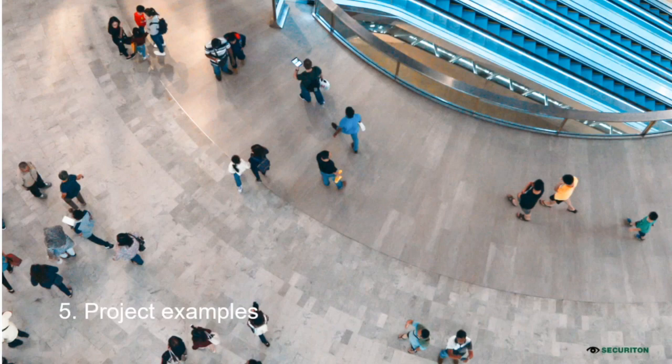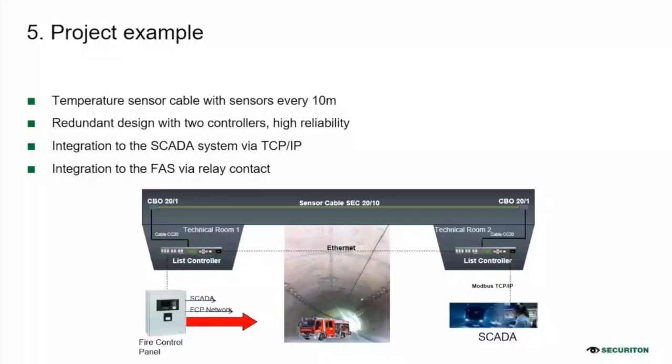Let's see some project examples, how this may work. If we see here a typical one-tube road tunnel, we have the temperature sensor cable with sensors every 10 meters. 10 meters, this is more than enough. You don't need to have a location every meter, because if there is a fire, we can see very easily where the fire starts from far also. That's why 10 meters is like a standard in a normal road tunnel.